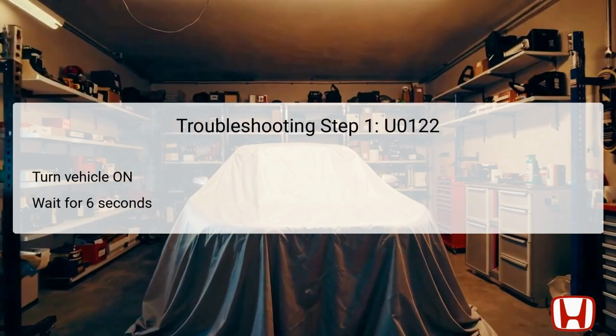The first troubleshooting step for DTC U0122 involves turning the vehicle to the on mode and waiting for a brief duration of 6 seconds. This step is critical, as it allows the vehicle's systems to initialize and perform self-checks, which can provide valuable diagnostic information. By following this initial procedure, technicians can determine if the DTC reoccurs in the system.